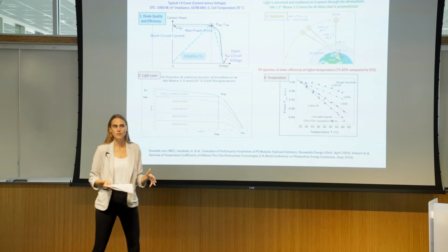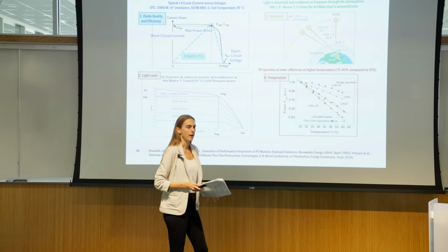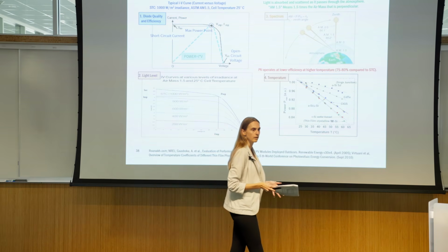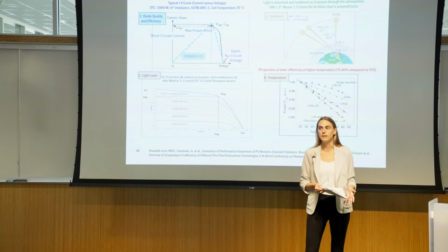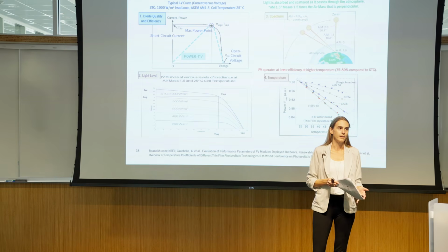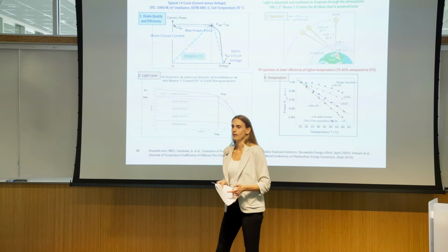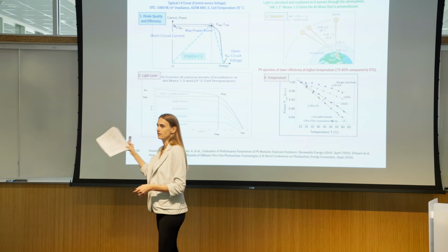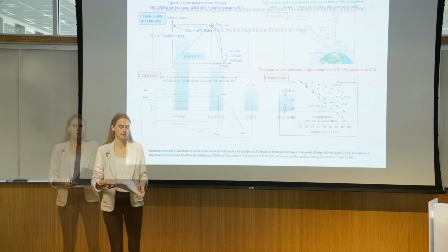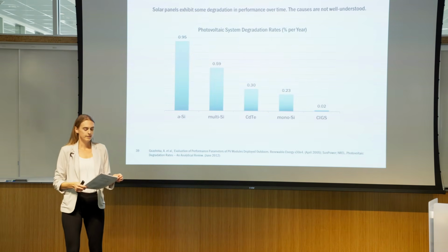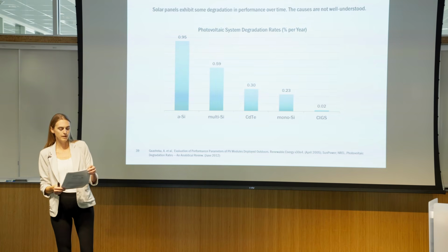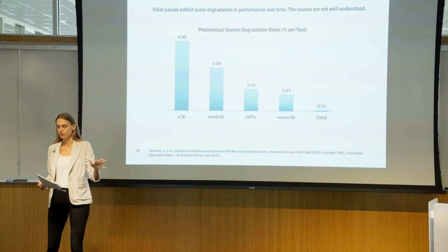You know, oftentimes when you're looking at Wood Mac or Green Tech Media data on solar capacity, they're providing it in DC. And I've seen folks make the mistake of comparing that to other power data provided in AC without making that conversion.